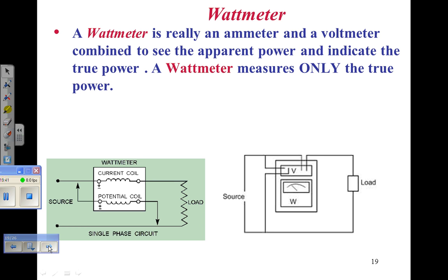Let's say it's taking in 1,200 VAs. That's terrible efficiency, isn't it? Is that possible? Believe it or not, that's fairly likely. 746 divided by 1,200 is 62% efficient. That's a little below the national average for code book motors. Most of the motors that the code book looked at way back when were very low efficiency motors, like 70% motors. Well, motors have gotten a lot better than that, but we won't get into that.